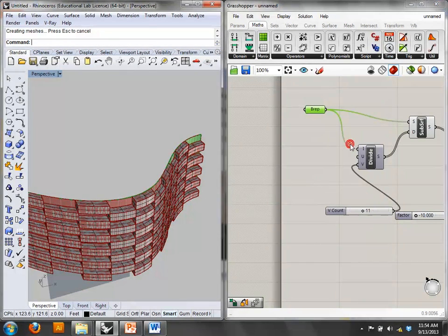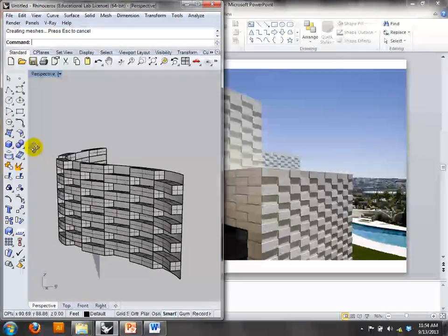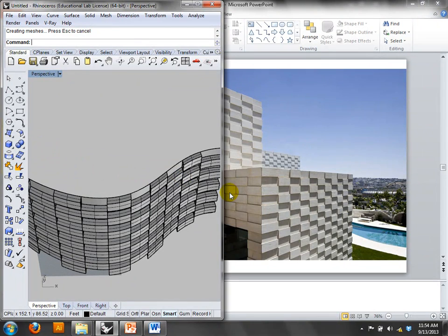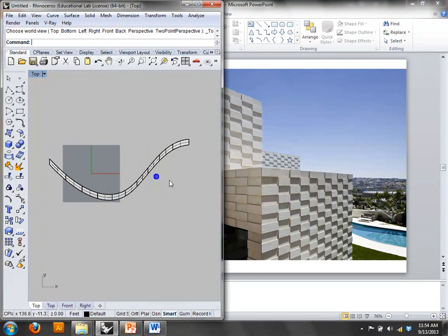And bake. Okay. So you might be okay with that, but it definitely is not the same. It doesn't flow like with the surface, right, when you extrude it. Okay? So this is where you need that pattern that we just showed for like Heatherwick, where it's going to adapt to the surface, to the local coordinates of the surface. Right? If you just extrude it in the Y, that's what it does. It's just going to take a straight line and pull it out in the Y.